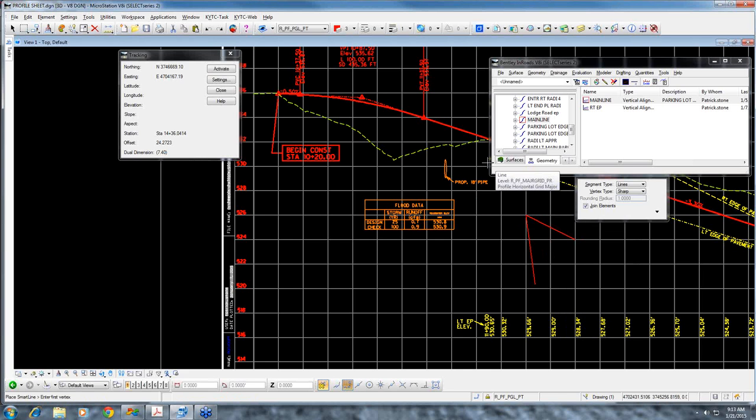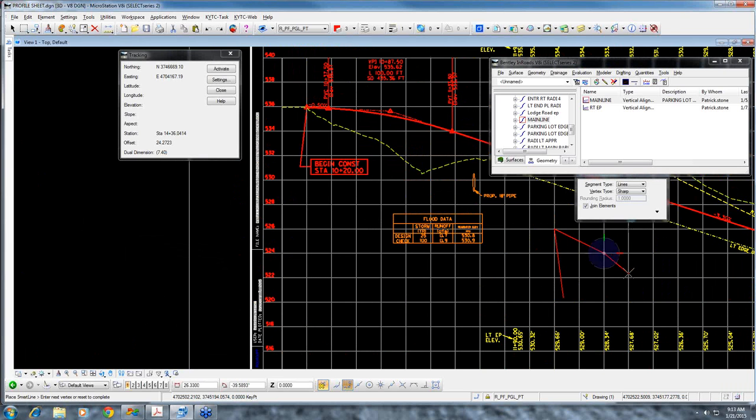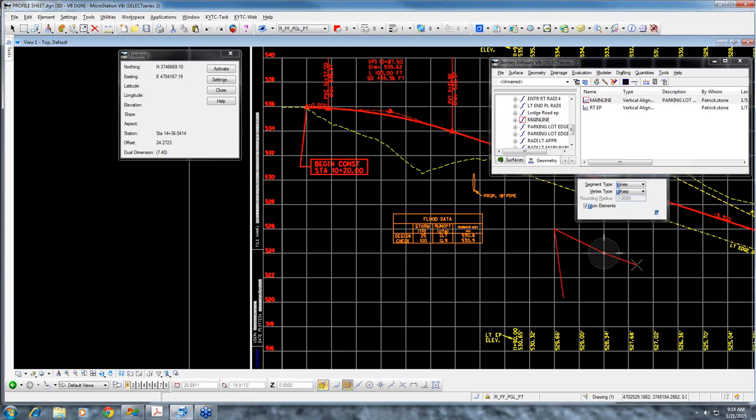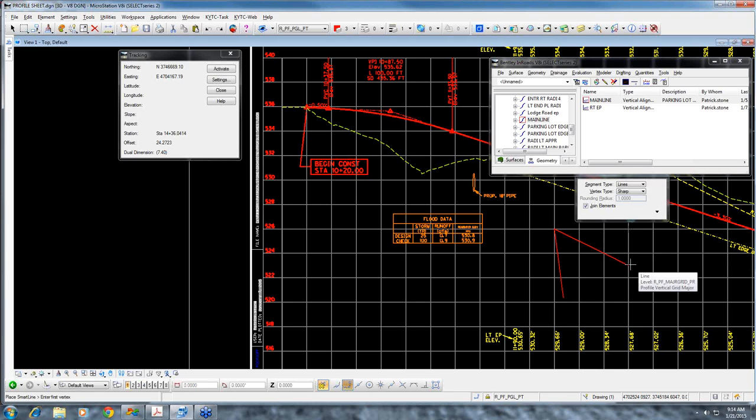Now, one thing, I don't use the delta offset much, but you may find a use for it, and all it's doing is going from the last point. Like if we want to do a delta offset from here, these are 20-foot grids, I believe. Yeah, if we want to go 20 foot over and 1 foot down, should hit right about there. Well, let's see what I'm doing here. I'm sorry. That's not distance grade. It's delta offset. Like I said, I don't use that much. So anyway, that will be your delta deal there.